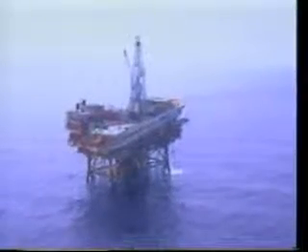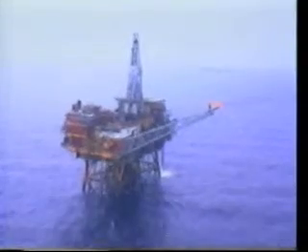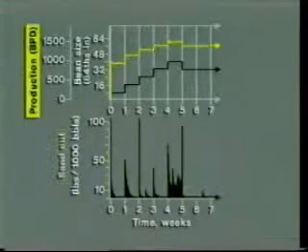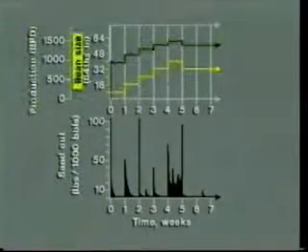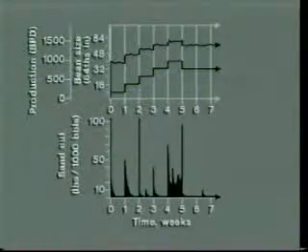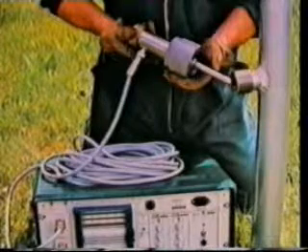Probably the most consistently accurate method to determine whether sand problems will exist at a given reservoir pressure is a properly conducted production test where sand cut, production, and bean size are recorded. This type of well test should have sand detection equipment at the surface and downhole if possible. The test should consist of a step rate test for extended flow periods.